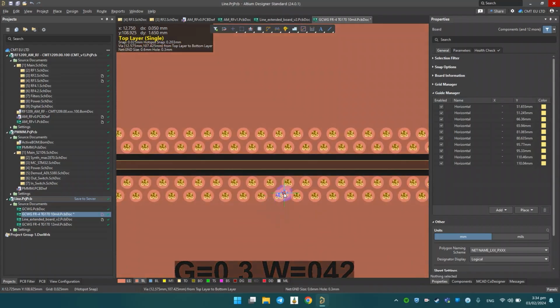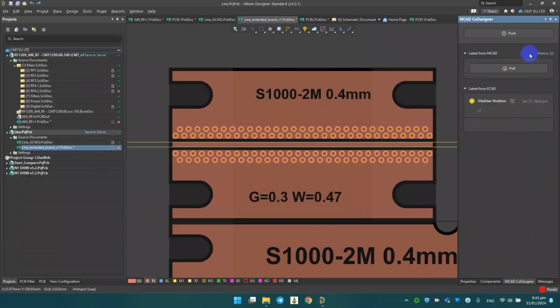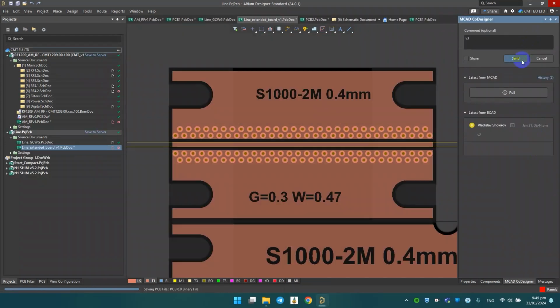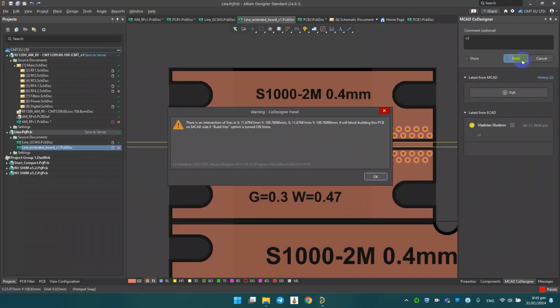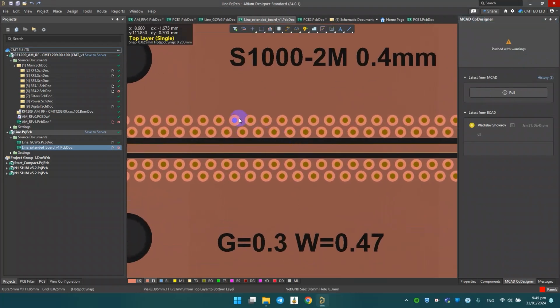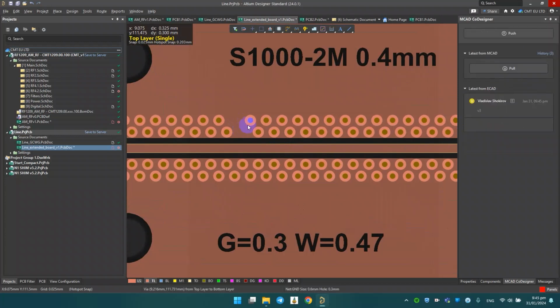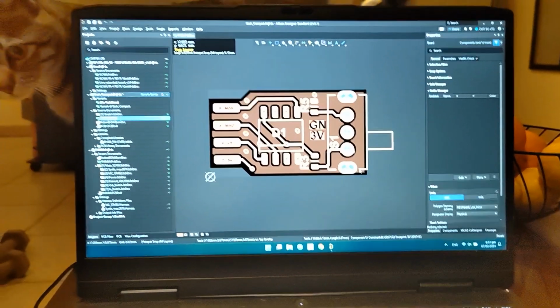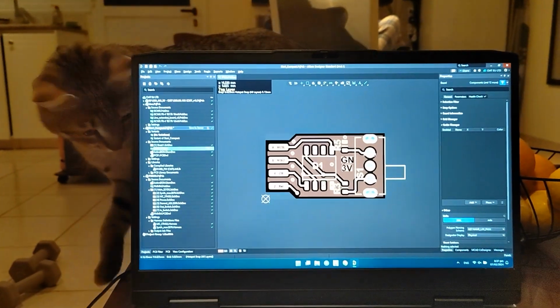There's a situation when a via is in one place, and when trying to send the board to the manufacturer, you see an error. What did I do in this situation? I would look at the coordinates and try to find the points where there are 2 vias, or start deleting them to find duplicated elements. I can already see my cat's dissatisfied look.